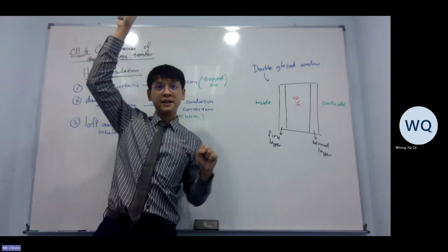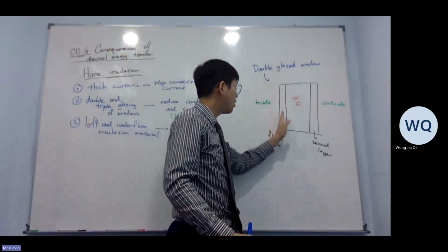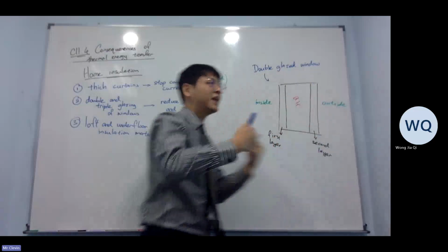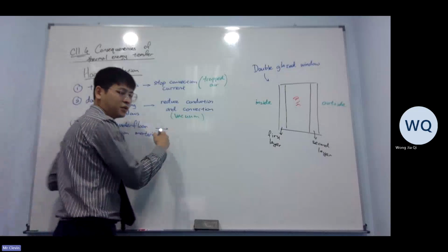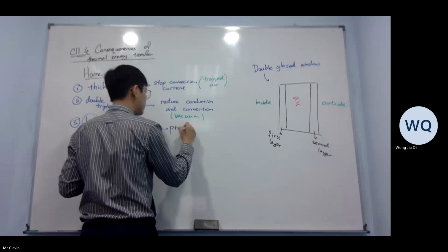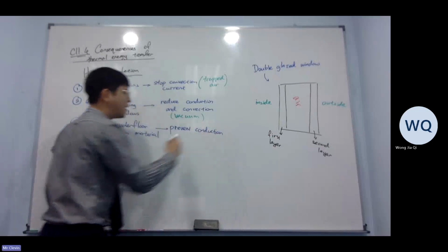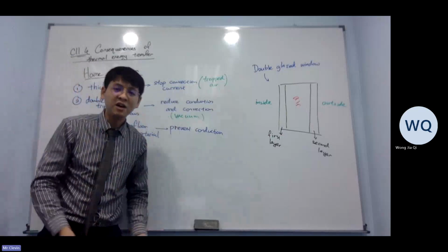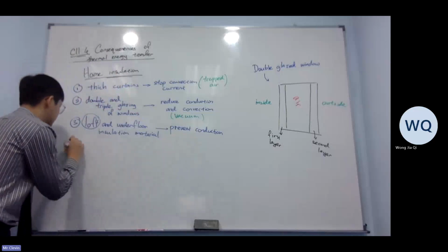Second, at the ceiling, they put foam first, then a board. And in the wall, they put one layer of bricks, then foam, then another layer of bricks. Why do we want this? It is still to prevent conduction. How does it prevent conduction? Same thing, trapped air. In any foam, there must be trapped air. That also prevents conduction.